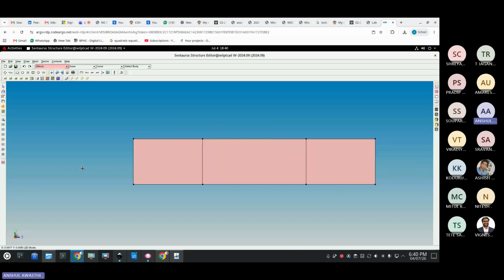Now I want to define two gates. Before the gate, there will be an oxide layer. So I have to select the oxide from here. I have to change the material. Don't forget to change the material. So I'll change it to oxide. The oxide will be only where my gate is. The gate is from 30 to 75.